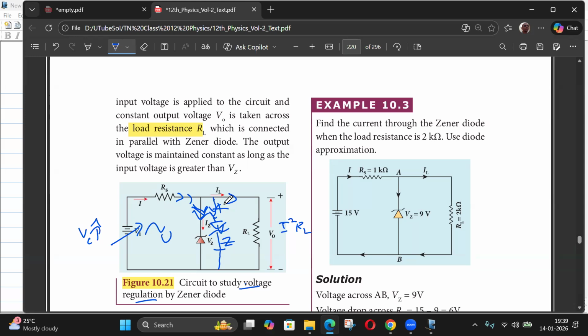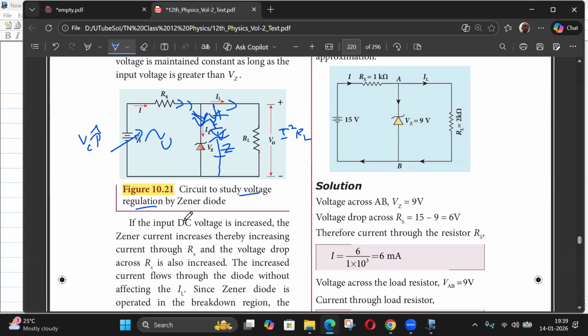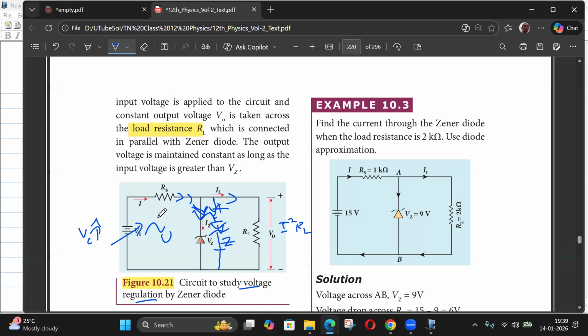It's not in your book, but I'm saying it for the sake of completeness. Because AC segments will be positive and negative. During positive, this thing will absorb the current. But when it is negative, this will be forward biased. So if I connect one more thing in parallel with the opposite polarity, then this thing will take the current when it is negative, during the negative cycle.